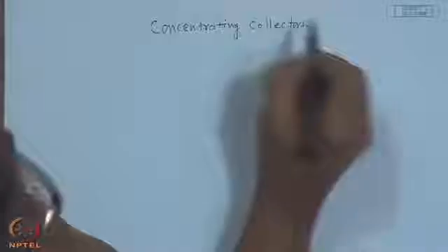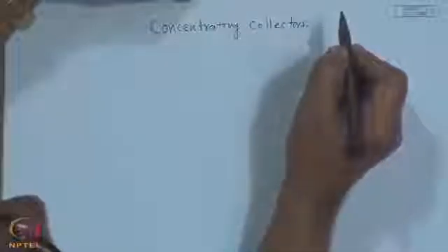So, we go on to the next topic of concentrating collectors. We explored improving the efficiency or the operating temperature for the flat plate collectors through one or two or more glass covers, better insulation and even evacuation, though it may or may not be practicable to have a completely evacuated flat plate collector. So, the next idea is to have what we call concentration, and the very early type of concentration you can see in the form of mirror boosters.